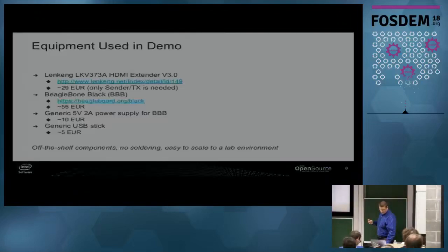So, I have been looking and trying quite a few different things, and I've come down to these for at least the current time, so I'm always looking for the next alternative. It's not a Raspberry Pi, unfortunately, it's a BeagleBone Black, because the Raspberry Pi won't give you the USB gadget, and the Raspberry Pi Zeros that do get you that, you have to do soldering if you want to power them from a DC power supply.